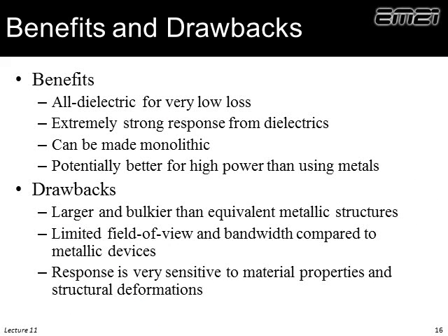So why on earth would we even be interested in guided mode resonance filters? Well, at optical frequencies, metals are lossy. This is a way that we can produce a filter response that's very low loss. We can have near 100% efficiency from these. Also, what's neat, these are all dielectric. Typically, we don't get that strong of a response from a dielectric structure, but the guided mode resonance phenomenon can produce a very strong spectral response, even with just low refractive index materials.